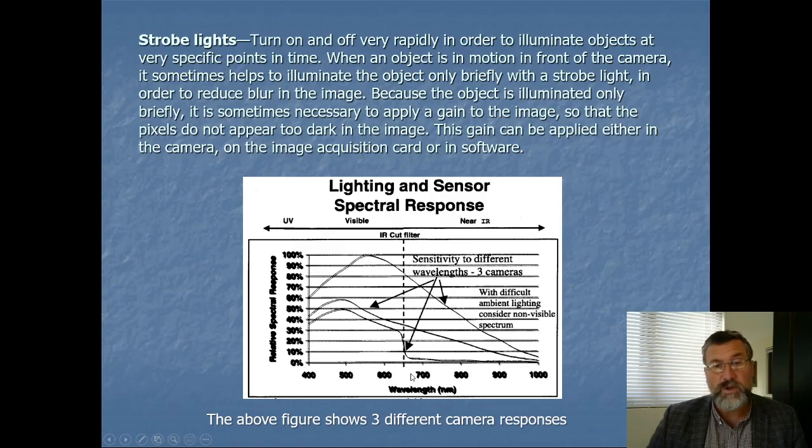But the problem was that we wanted to image the light here, so we didn't want this cutoff because we were trying to get a good sensitivity like this. So what we did, we took out the IR cutoff filters, but that altered the focusing of the camera. So we had to buy from Sony some dummy filters and put them in place of the IR cutoff ones, which worked okay, and they got it working in the States. They're selling the system. They sold it to various airports around the world to measure freight. San Francisco Airport, Amsterdam, using the system now.